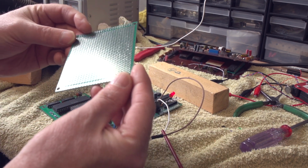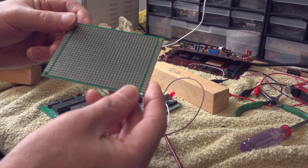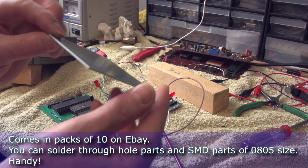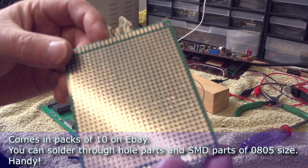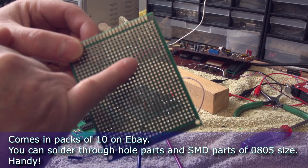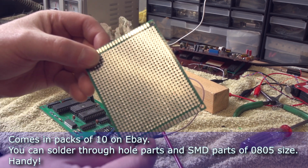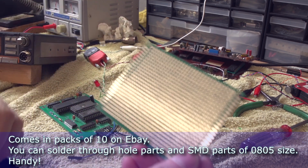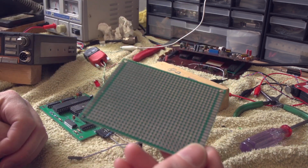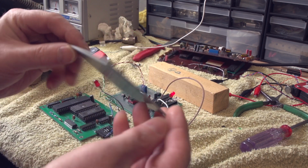Really liking this stuff. You get it off of eBay and places like that. It's not expensive. You normally get them in packs of 10 and stuff, and all it is, you know, it's soldered islands, if you like, per pin. It's not copper strips like Vero board. It doesn't connect all the way through, and I'm finding this stuff really handy these days. I'm using quite a lot of this for prototyping, so yeah, little tip there. And it's pretty cheap on eBay.